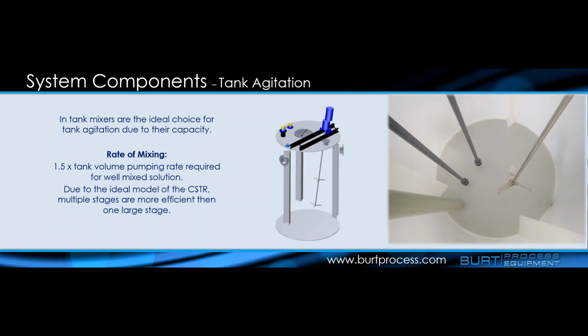In the example I'm showing here, we have our chemical injection located here at the top, and then they basically have down pipes going in. You can see in this picture as well. That just basically drips into the solution right into the mixer backwash. By utilizing a recirculation pump for chemical injection, you're now injecting into a pressurized line, and then that fluid is utilized as a carrier medium and educted into your mixer backwash, which gives you a much faster rate of injection. So that's generally where you would see recirculation pumps used, and that's done a lot on either much larger systems where ergonomics comes into play, and you don't want to be having injection going into a tank that could be 10 feet tall, or where you have a very strong waste stream. This will help speed up your reaction time within your system.